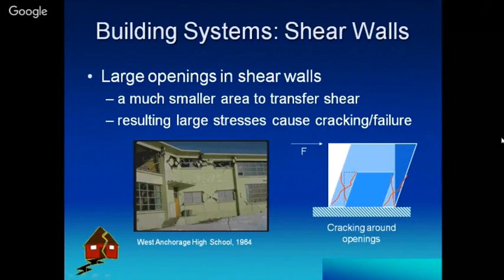So every wall which is having earthquake force parallel to it, that wall we will consider as a shear wall, and accordingly we will analyze and design that wall, because the wall just perpendicular to that particular shear wall is not going to participate much for that particular earthquake load which is parallel to that shear wall.